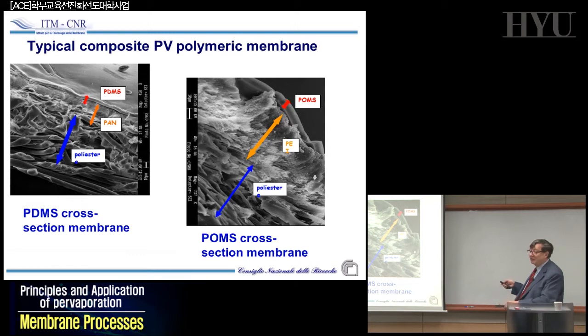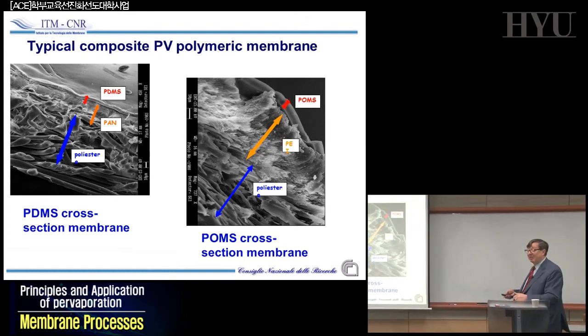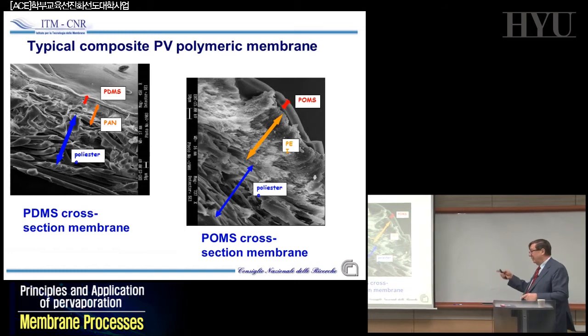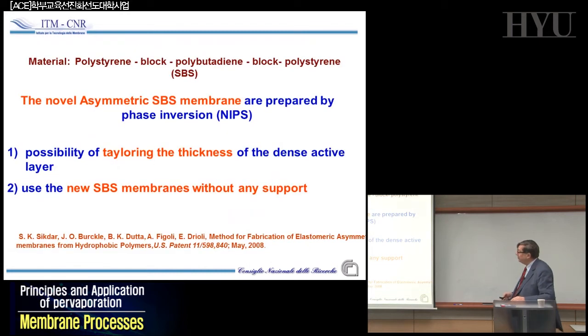But when you pretend to always have a 1 to 2 micron dense skin, and the other has to be porous, etc., that's the reason for which you pay $1,000 for the same polymer, polypropylene, that, if you just use it for making plain, costs you a few cents of a dollar per kilo. If you make what is called in some cases Accurel, for example, it costs you $100 per kilo, because it's not easy to keep control of the final morphology of the system.